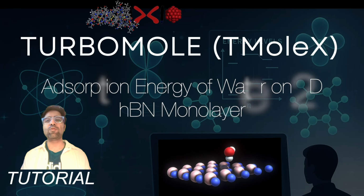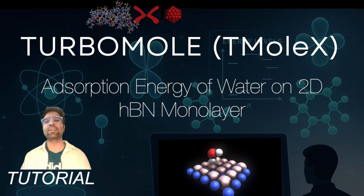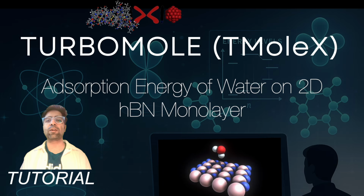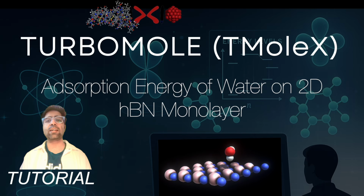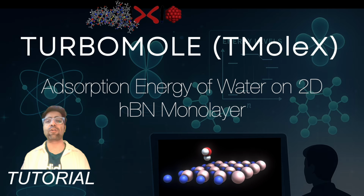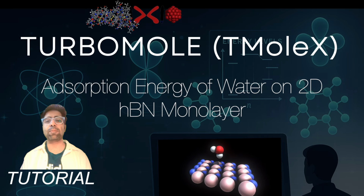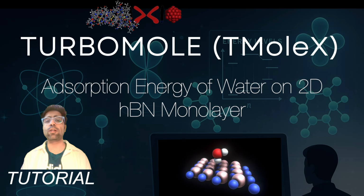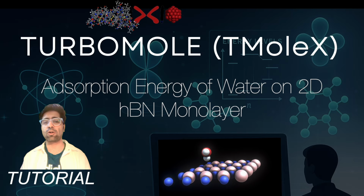Hello everyone and welcome to another tutorial on Turbomole and its graphical user interface TmoleX. In this tutorial, we'll be working with some 2D materials and employing density functional theory calculations with two-dimensional periodic boundary conditions. As an example, we'll be calculating the adsorption energy of a water molecule on the hexagonal boron nitride monolayer.